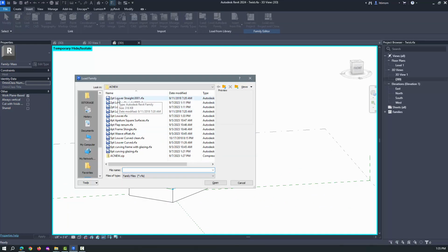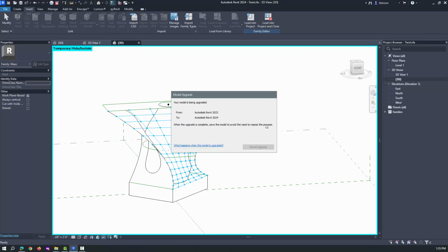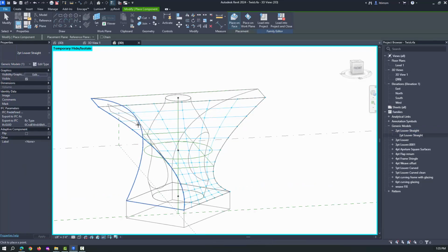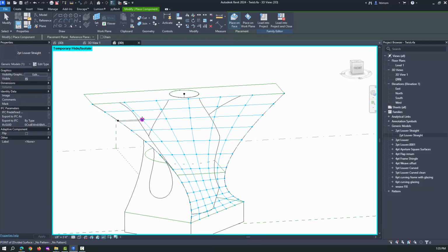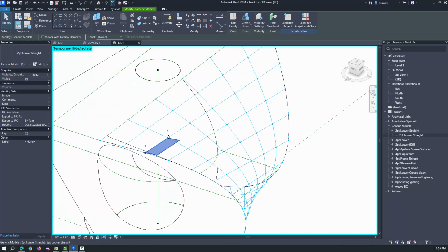And I gave you this bunch of components. So you can open those. And it'll load them. And if you expand your families, you'll see generic models. That's the category that they're in. So you can do something very simple, like take a 2-point louver and just pull it across here. So if I shift, there's that louver. And it's very important that it picks on those points, because then you can repeat it.